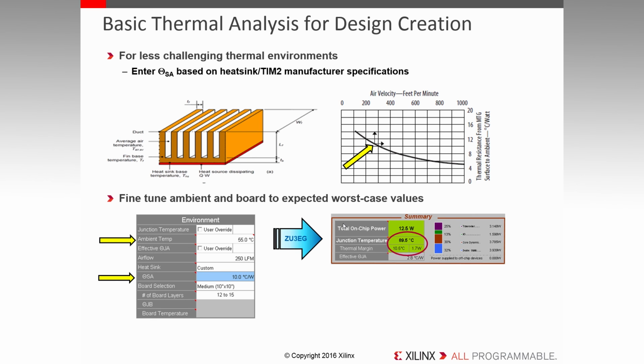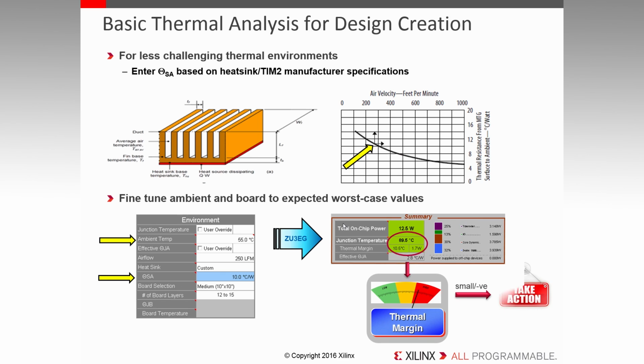limits. Also, XPE thermal margin indicates how close the estimation is with respect to the max limit, based on the thermal solutions you applied for this design. If margin is small or negative, then you need to take some action. Either go to advanced thermal analysis or improve thermal solutions. Could be an effective heatsink, more airflow, etc.